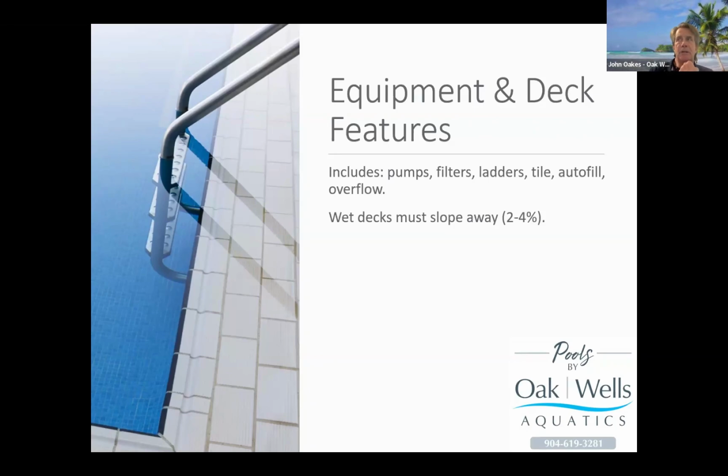There's also, if this is a DE filter system, a collection tank, which I mentioned at the very beginning, that the pumps pull water out of. And normally in those tanks, if we're using a DE filter, there's the filter grids. So all of that's packed into that pack. There'll also be maybe an ORP controller, but there's a third pump. That third pump is for pumping the tank out, so it goes to waste, for cleaning the filters.